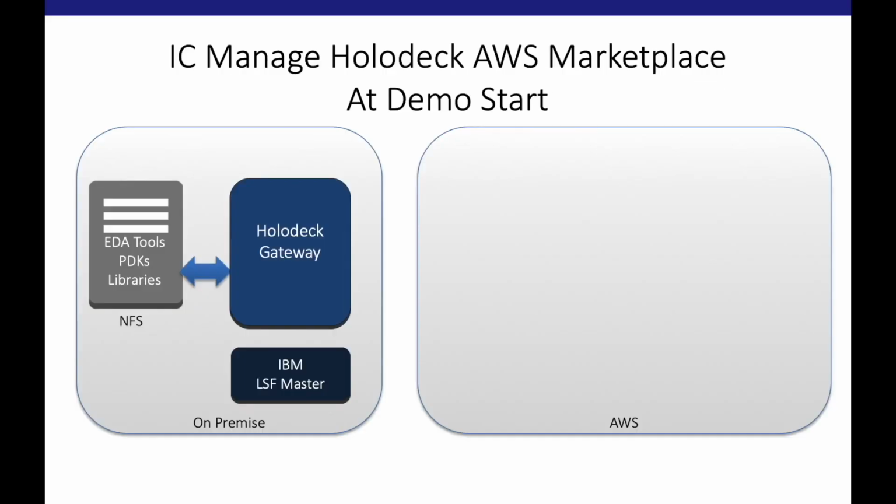Here's a diagram of our demo setup. We have the typical EDA tools, PDKs, and design source data on an NFS drive on-premise. The Holodeck Gateway is a service that connects to the NFS mount points and also contains an LSF job scheduling master controller that can run on-premise, but also starts and controls jobs and compute nodes in the cloud.